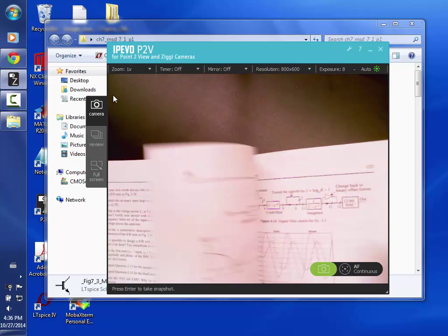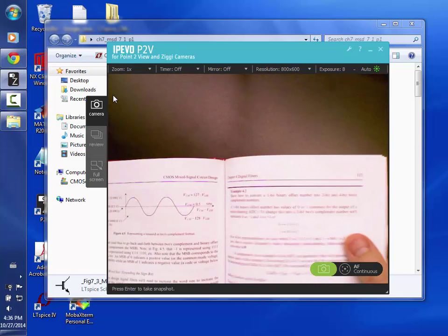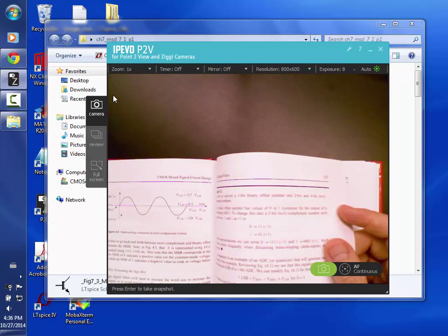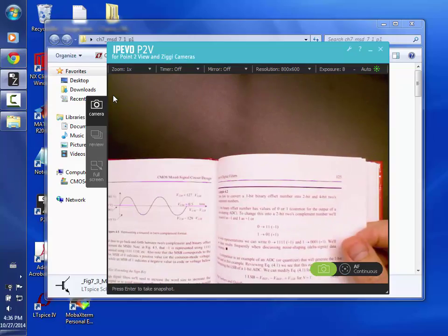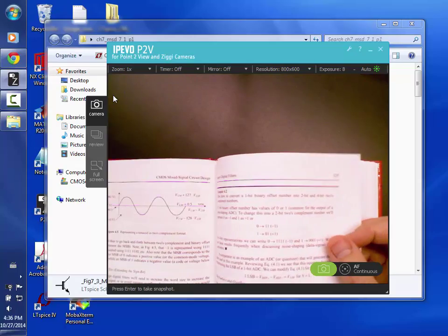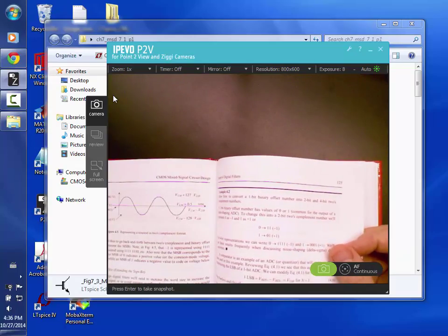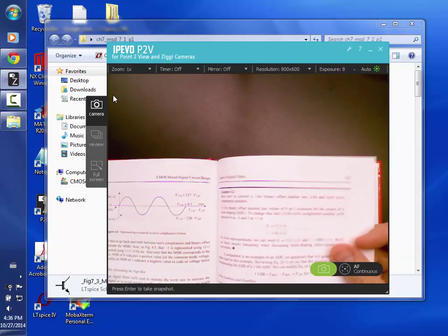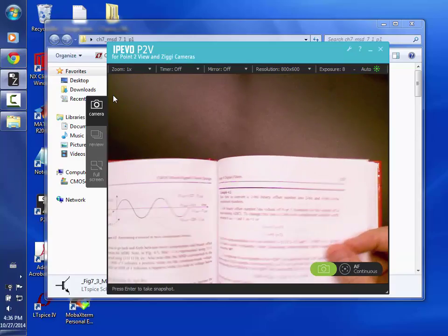Maybe it wasn't. Well, no, the problem is if you make your capacitor too big, then you choke off the bandwidth, and also you get too little of a signal to resolve for your comparator, because remember, you're using a real comparator, so if you reduce the signal levels, the comparator has a longer delay in making a decision.